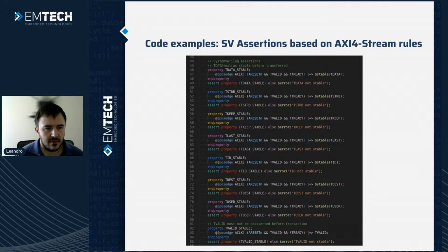Okay, and I think this is the last part. I included in the same interface below a number of concurrent SystemVerilog assertions, which are, I think, a very nice addition to Verilog when SystemVerilog was introduced, to support having some kind of checks in synthesizable code. This is not taken into account by the synthesizer, but you can introduce it in synthesizable code, and when you run simulations, this will actually fail if something's wrong.